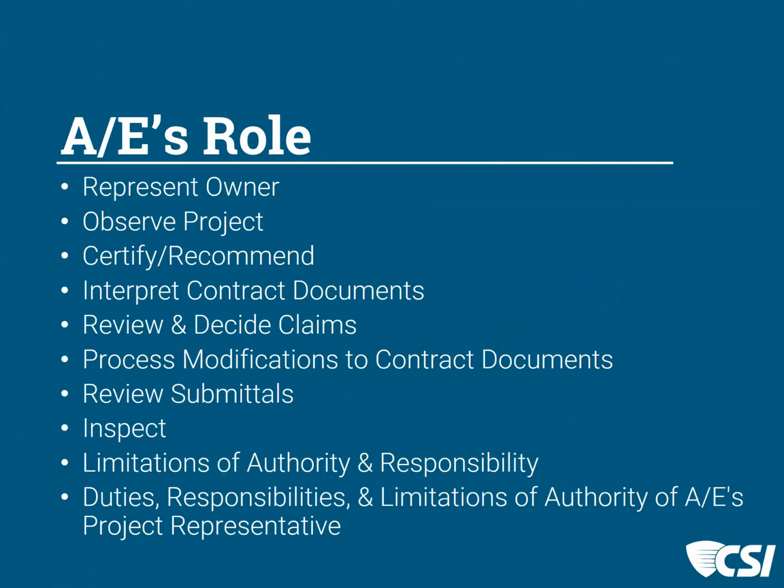One of our roles is to review and decide on claims, and that goes back to being on the fence and being impartial. We've got to process the modifications, whether those are change orders or additional information that the contractors need in order to do the project properly. We review submittals and we do inspections.